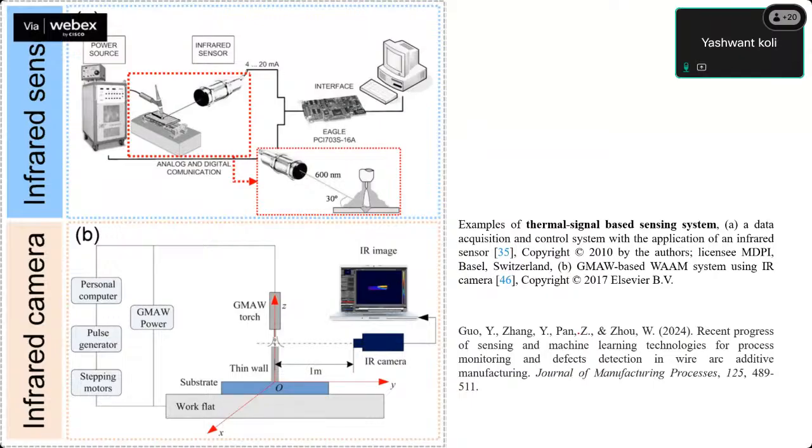First of all, infrared thermography and emissions can detect weld flaws like wormholes, incomplete penetration, and lack of fusion, with varying welding parameters, shielding gases, electrode, and base metal properties. So infrared emissions can vary with the process parameters.